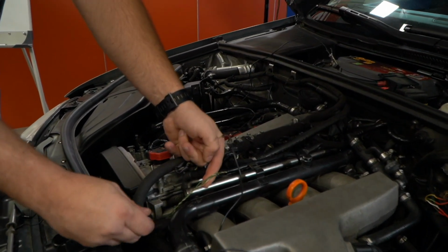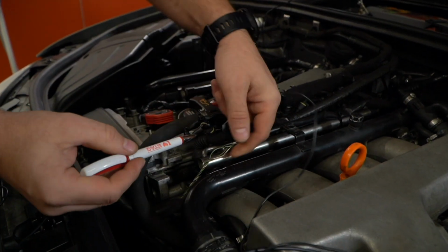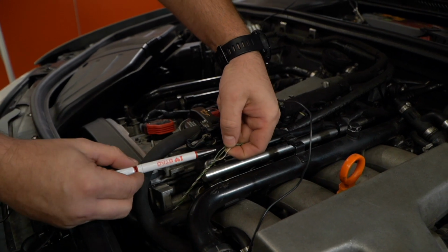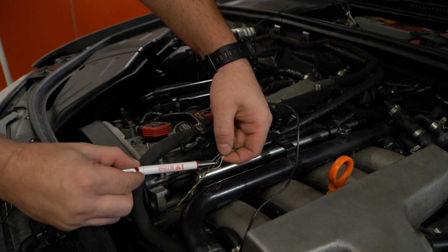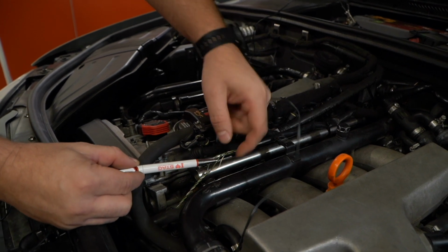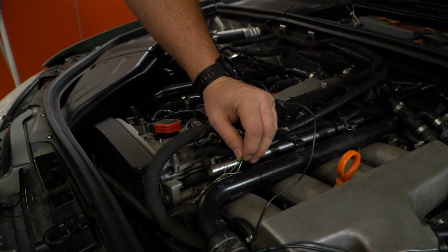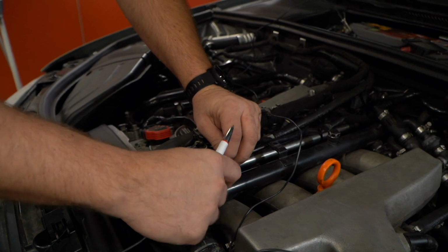The two sensors we are interested in are first the camshaft sensor, which is equipped with 3 wires. We already checked that on this wiring, one is the ground, the second is the power supply, and the third is the signal. So we will connect the oscilloscope probe to the signal wire.